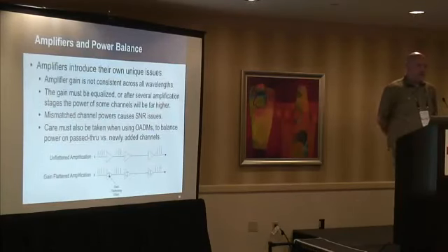When you're actually working with amplifiers, you need to balance the power. The gain is not always consistent across all wavelengths. You might have one portion of the spectrum that is amplified more than another, and there's a bunch of consequences that happen if you don't take care of this. You cause a lot of signal noise issues.